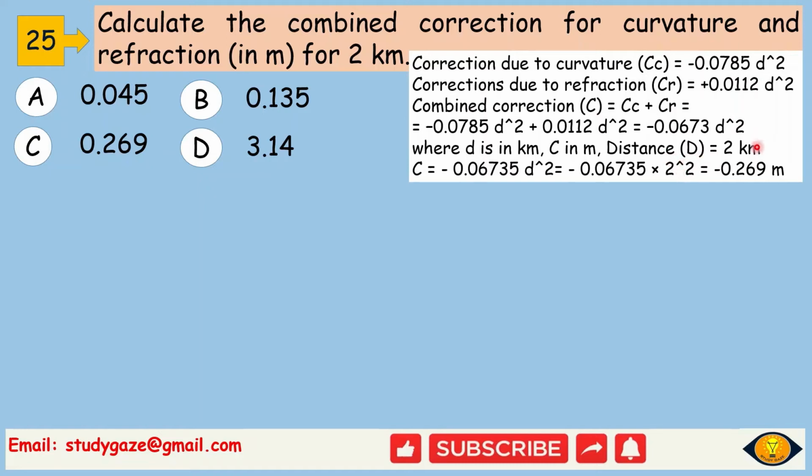So for distance d equal to 2 kilometers, C equal to minus 0.0673 into d square, that is 2 square, which will give you minus 0.269 meter. So the correction will be 0.269.